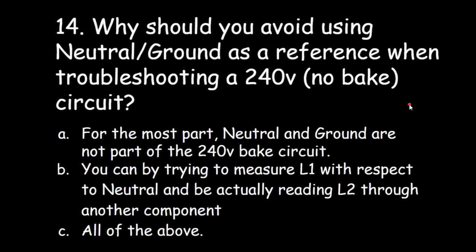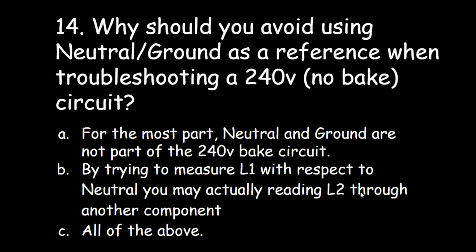Number 14. Why should you avoid using neutral and ground as a reference when troubleshooting a 240 volt no-bake circuit? For the most part, neutral and ground are not part of the 240 volt bake circuit. By trying to measure L1 with respect to neutral, you may actually be reading L2 through another component. Or all of the above. The answer is all of the above.